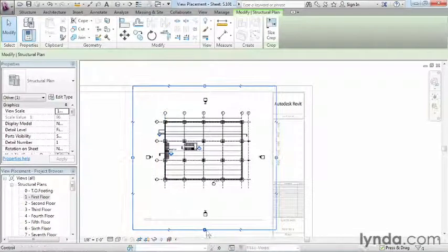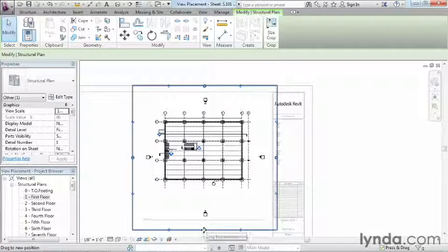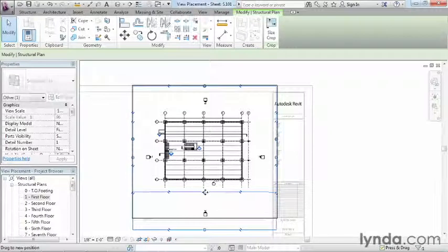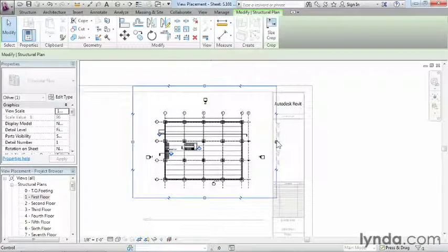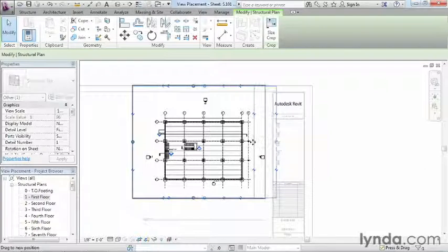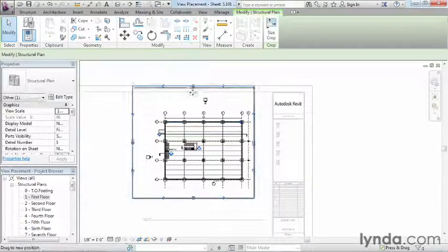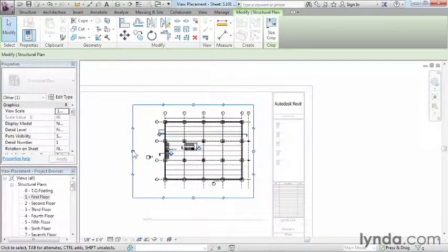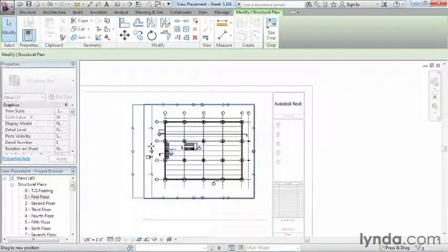And then if you click on that box and then hold down on the little grips that are around the middle of them, you can pull this box up and anything that is not inside of the box is then going to get hidden. It's going to get cropped out. That's the reason why it happens to be called a crop region.